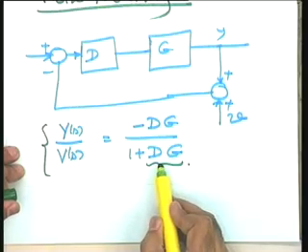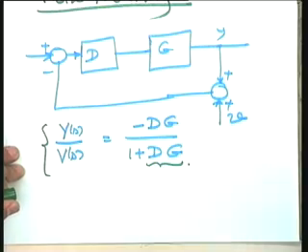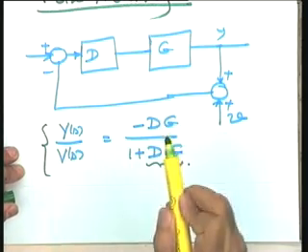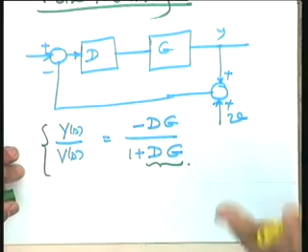Okay, well, as I said, there is always a trade-off in the control system design. You cannot meet all the requirements by increasing the loop gain. So what we normally do is the following, that to take care of the noise problem, we don't compromise on the loop gain, rather we introduce an appropriate high frequency noise filter.